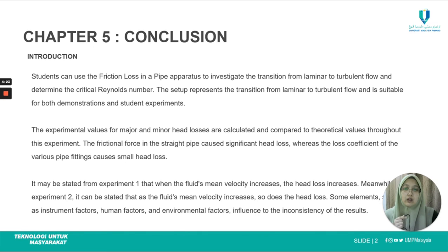So the experimental values for major and minor head loss are calculated and compared to theoretical values throughout this experiment. The frictional force in the straight pipe caused significant head loss, whereas the loss coefficient of the various pipe fittings causes small head loss.